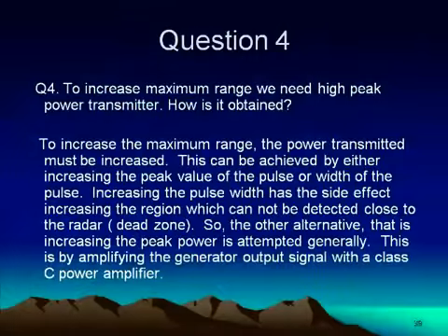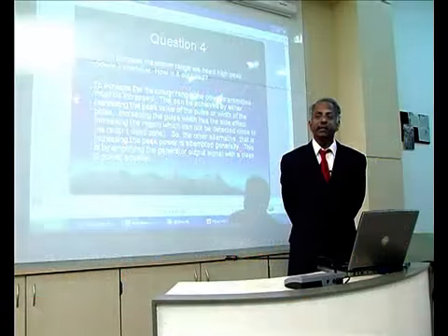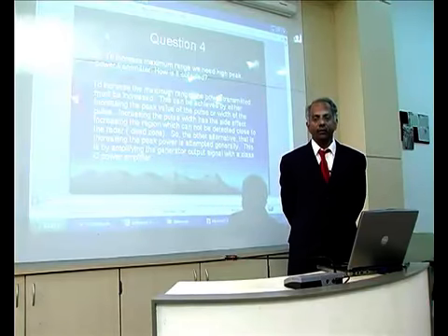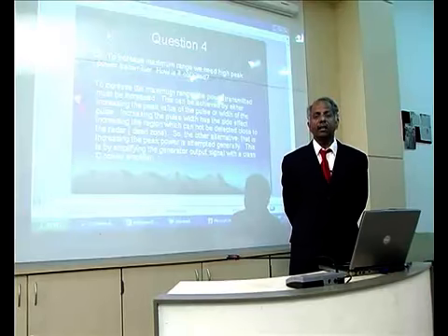To increase the maximum range, we need to use a high peak power transmitter. Now, how do we obtain such a transmitter? To increase the maximum range, we need to transmit more power as per the radar range equation.